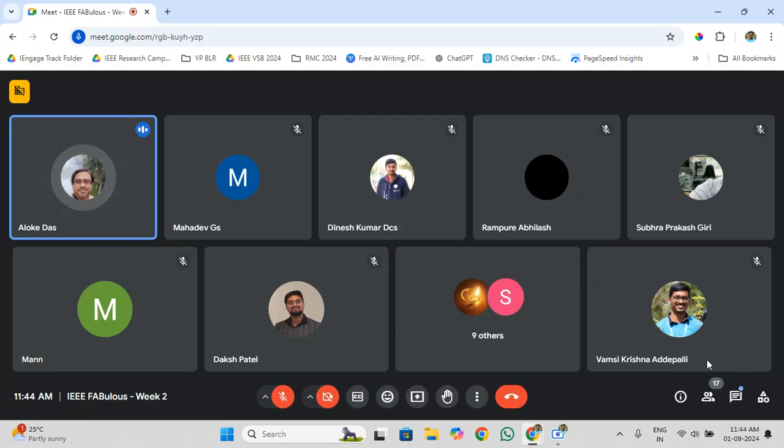And also there is another dimension, memory. You can design simple memories: 8 KB, 4 KB, 2 KB, 32 KB memory with 8-bit word, 16-bit word, and the memories can be digital, also analog. By analog side means 6T cells. You can design that thing, but design a big memory so that it can be usable. And in this project we can manufacture memories also, for your information.